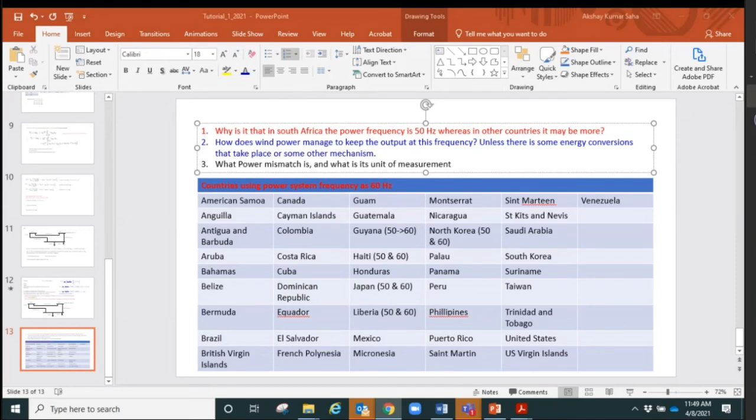Now when we do load flow study, we will calculate P and Q. So the difference between P injected and P calculated is actually the power mismatch. The difference between Q injected and Q calculated is the mismatch. You do one iteration, you get one mismatch. You go to the next iteration, you get another mismatch.